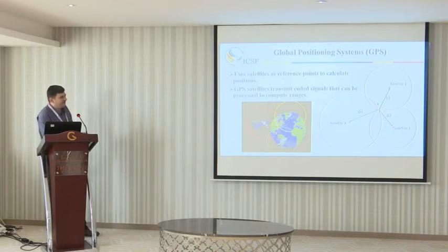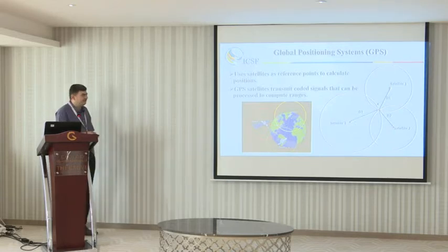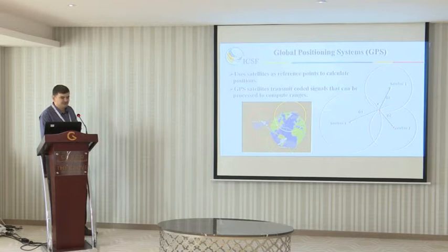Three will give me my location. It's just a matter of mathematics, least squares, anything. In GPS, there's an extra unknown, which is the clock of the receiver. So normally three satellites is not enough in GPS. We have to have at least four satellites to achieve the minimum accuracy required.